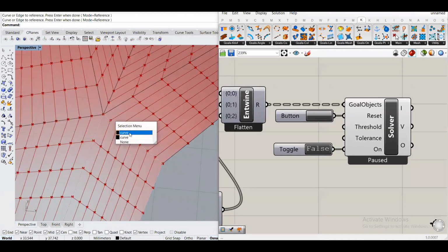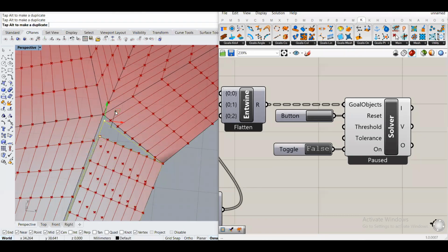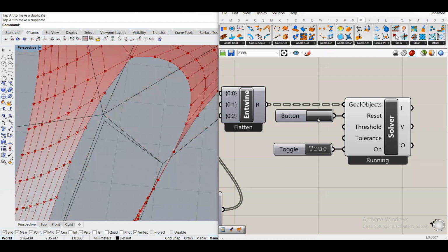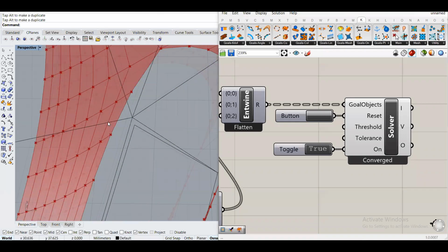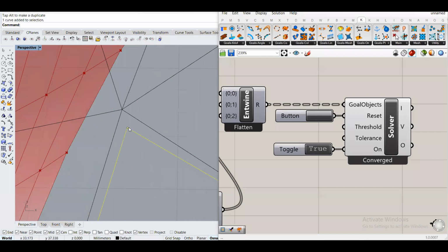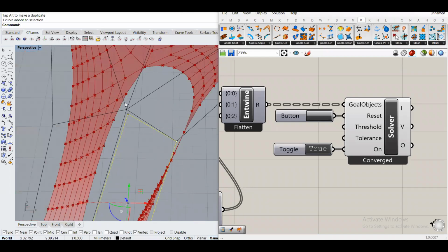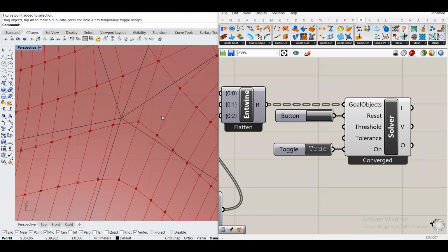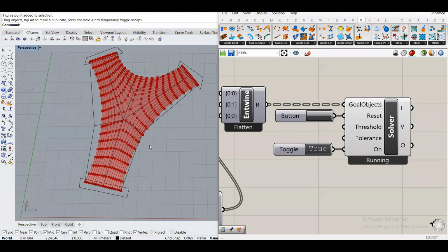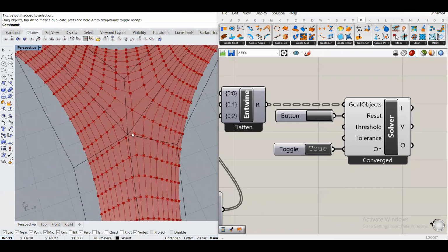Let's see. Is it something like this? Okay. Notice what I have done here. The corner point doesn't align with other corner points of the rectangle. That means you haven't snapped it properly. So if the rectangles are not aligning, it's going to start making holes for you.